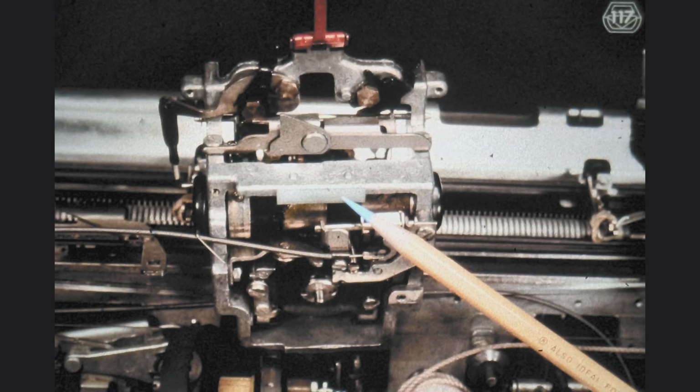Notice this nylon shoe called the buffer. It touches the carrier support rail during printing. Depending upon the level of your machine, you might have a buffer of a completely different design. Earlier models had adjustable buffers. This one is not adjustable. In this case, we must adjust the position of the carrier support rail.